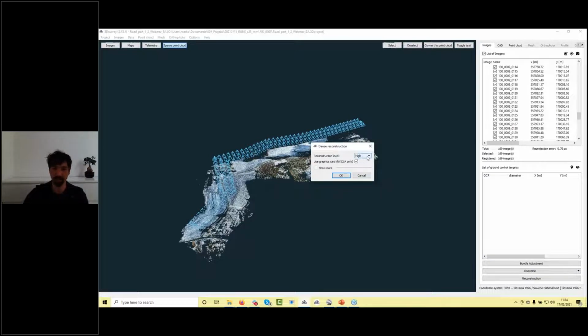For that kind of project where you have really a lot of data, big point clouds, long distances, I advise you to use the reconstruction level medium, because it's already good enough. You will see all the necessary detail out of it. And if you later join more flights together, you are not having 500 million points or something like that.